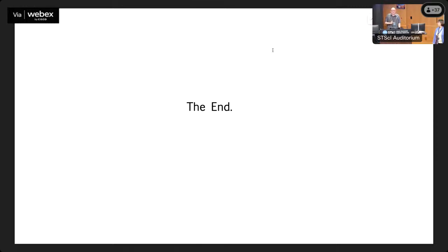In practice, this doesn't work so nicely because this is a very small decrease. What you observe in practice is that at some point, which usually is very abrupt from one basis function added to the set to the next, you will not find a full solution anymore which is smooth. Usually you can assume that the overall passband is smooth, and you will find that if you add one more basis function, you cannot get an orthogonal component that makes the sum smooth anymore. This is, in my opinion, the best indicator that you have reached a point where you pick up too much noise and you cannot get any meaningful result anymore. So I would stop at the point until I can get a smooth overall solution for my total passband, adding the components. And this works in practice quite well, I think.